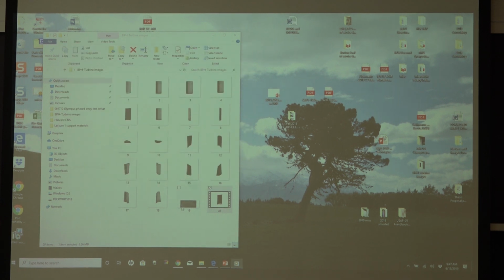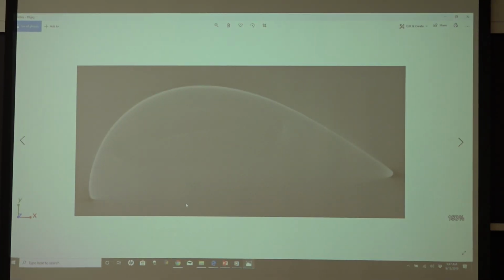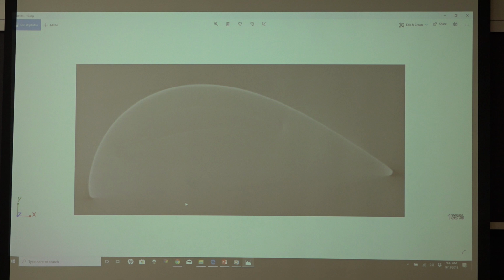If we're looking at the individual angles, this is what happens if you don't fully penetrate through. As we were trying to determine what X-ray was needed, I think this was something at maybe 70 keV, and at 70 keV you see the X-rays don't fully penetrate. If you know what material you're working with, you can look up what X-rays will generally be needed, but it is dependent on the longest dimension.